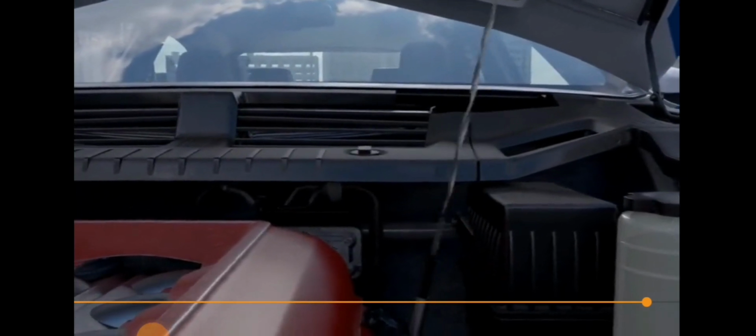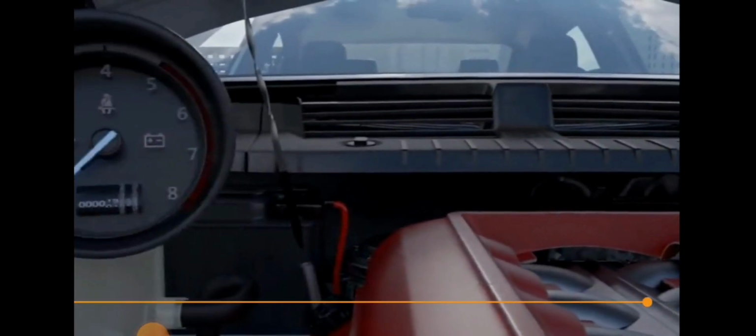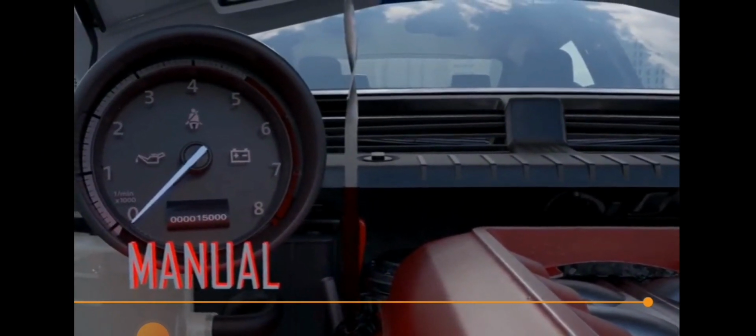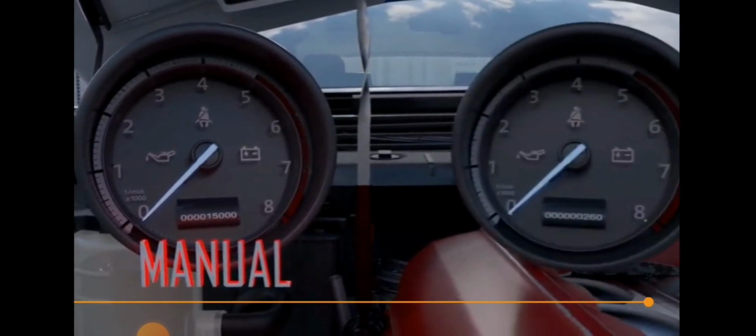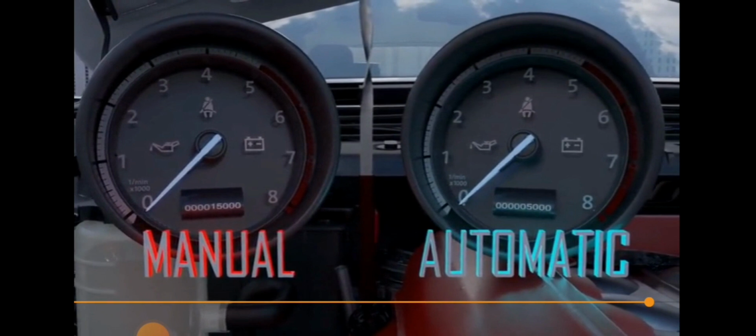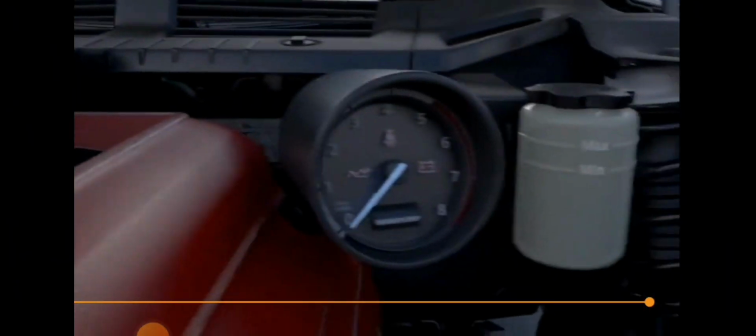Transmission oil. Manual transmission oil is checked every 15,000 kilometers in maintenance stations underneath the vehicle, and oil level in automatic transmission is checked every 5,000 kilometers by the scale allocated for this purpose, as shown in the figure.